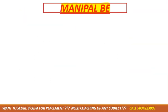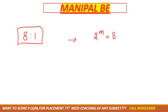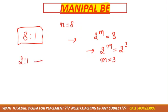Correct? If we have an 8 is to 1 multiplexer, then again we use the same formula. In this case n is equal to 8. How many should be the select lines? 2 raised power m is 8, so m should be 3. So for 2 is to 1, 1 select line. For a 4 is to 1 multiplexer, 2 select lines. For an 8 is to 1 multiplexer, 3 select lines. Correct?